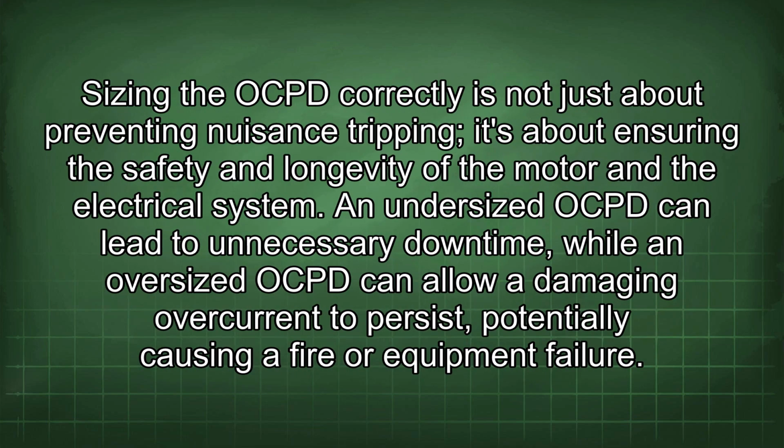Sizing the OCPD correctly is not just about preventing nuisance tripping, it's about ensuring the safety and longevity of the motor and the electrical system. An undersized OCPD can lead to unnecessary downtime, while an oversized OCPD can allow a damaging overcurrent to persist, potentially causing a fire or equipment failure.